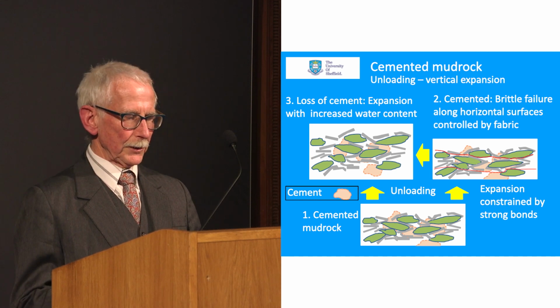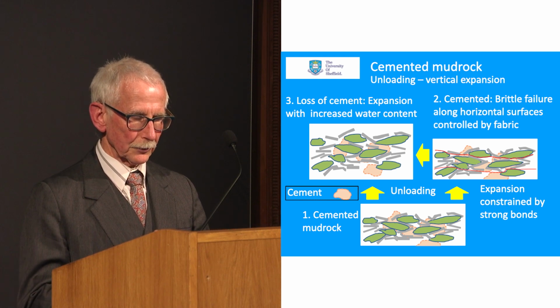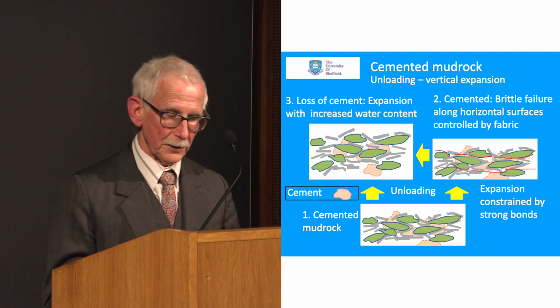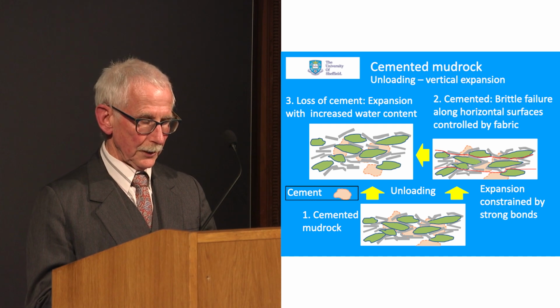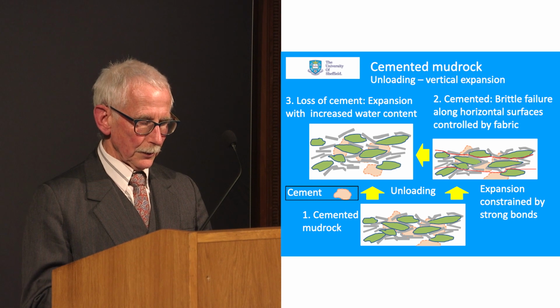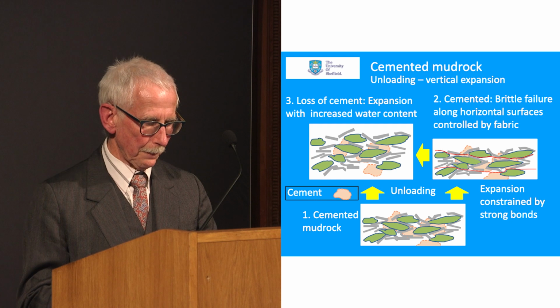Because horizontal expansion is more constrained than vertical expansion, high values of horizontal stress can be created, giving rise to fissuring and deformation of over-consolidated clays and explosive rock bursts in excavations in stronger mud rocks. Once the bonding is weakened, the rock can expand by increasing water content.